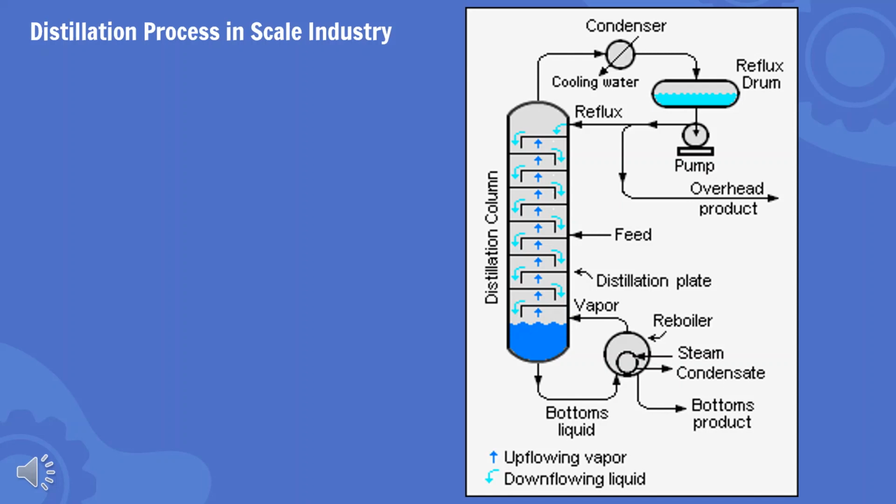As the liquid heats, components with the lower boiling point will begin to vaporize and rise through the column. However, the vapor will still contain some molecules of the other substances. Vapor gets purer the higher it rises in the column, as heavier molecules fall off and turn back to liquid. As vapor rises in the distillation column, heavier molecules will condense back into a liquid and run back down.